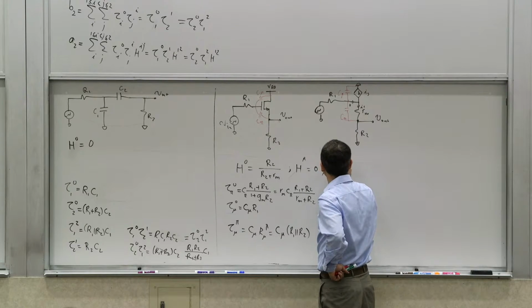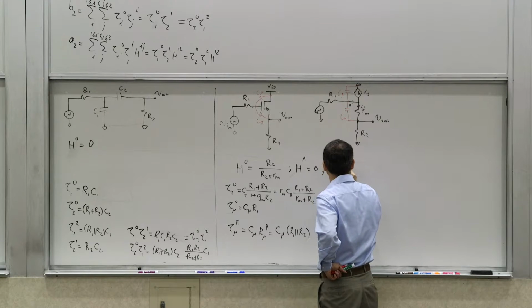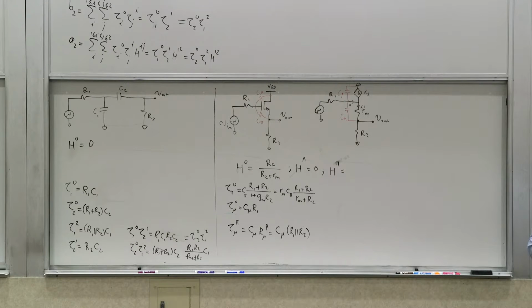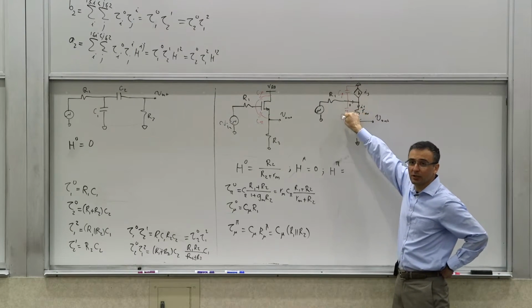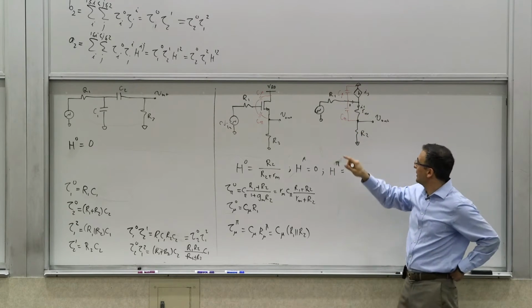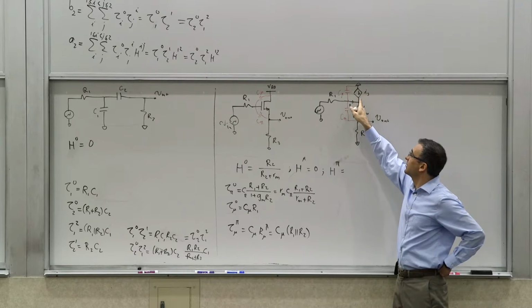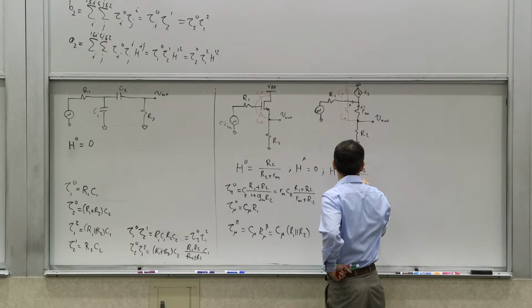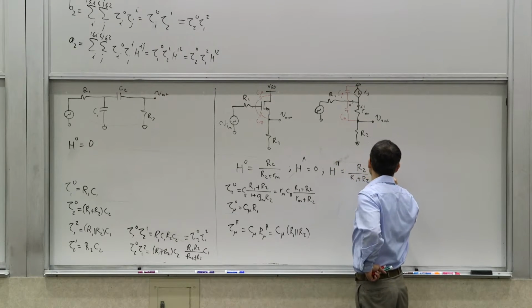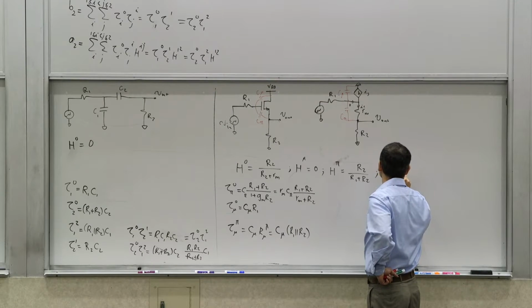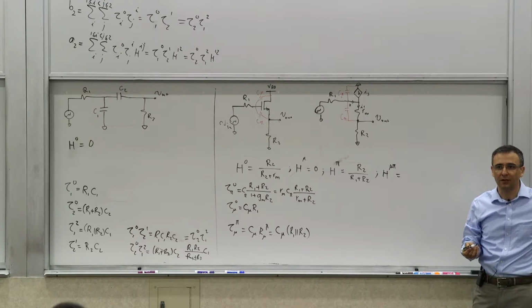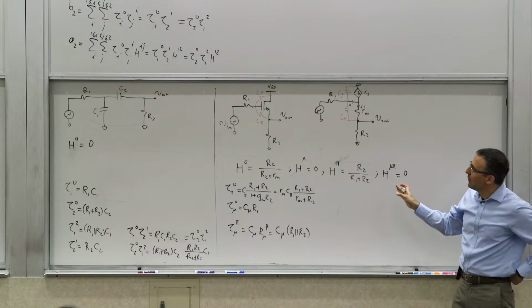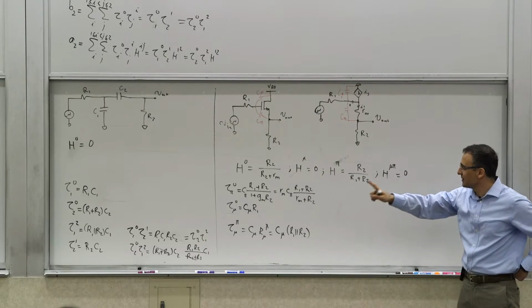How about h pi? What is h pi? That's a non-zero one, right? I mean, so to this you short circuit it. The R1 to R2. Yes, then you get the voltage divider between R1 and R2 because this is short circuited. This guy disappears anyway because that current is 0. So you get basically what? It's R2 divided by R1 plus R2, right? And then there's the h mu pi, which is what? If they're both short circuited or infinite valued, what do you get? 0.